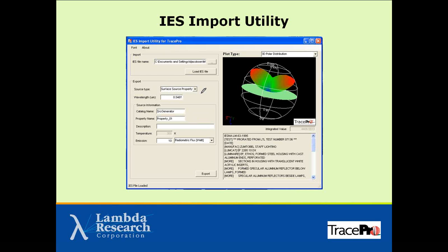TracePro also gives the option of creating IES files from the candela plots. So if you're working that and you have another program that you're using, say something like Lightstar from Oxytech, where you want to visualize the light source you've designed in a room, you could export the IES file and then load it into a program like that and see how it looks in an architectural application.